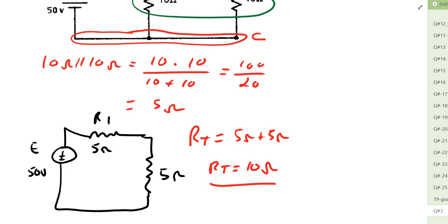Okay, now, generally, at this point, what we will do is we have kept our calculations now for equivalent resistance on the left side of the page, and so one of the techniques you might find useful is that now you can go and start at the bottom right side and analyze the equivalent circuits we've drawn to work our way back up to the top and complete parts B, C, and D as we go.